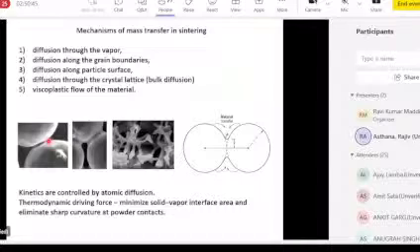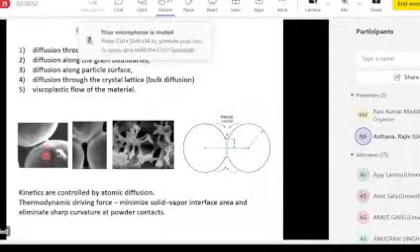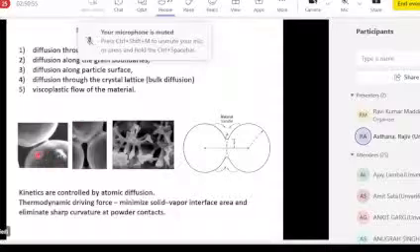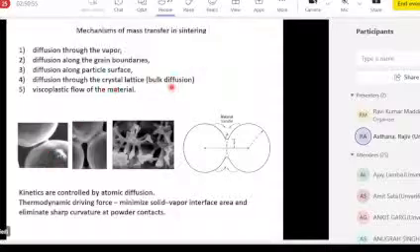as you call it. Atoms diffuse towards high curvature regions and deposit there to minimize the free energy of the system. And diffusion can take place through the vapor, along the grain boundaries in the powders, along the surface, or via bulk diffusion.